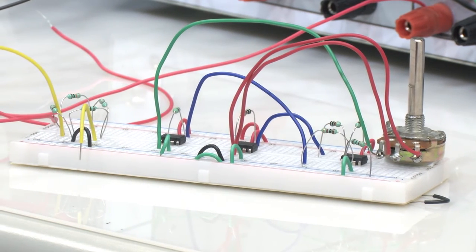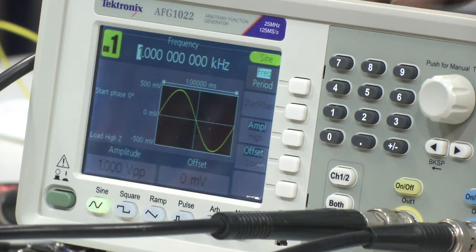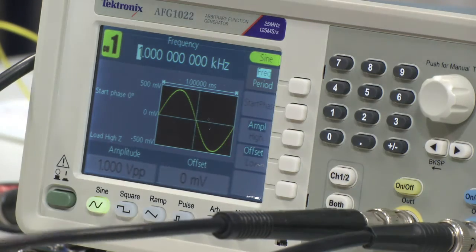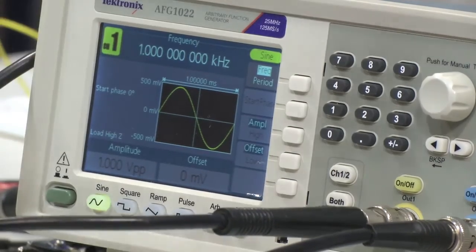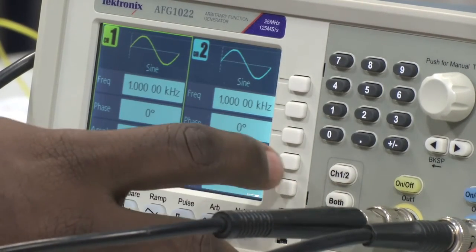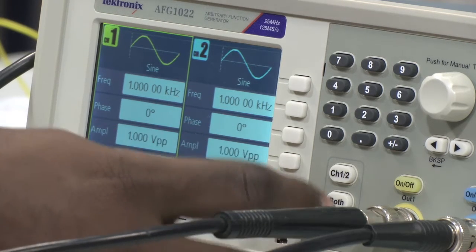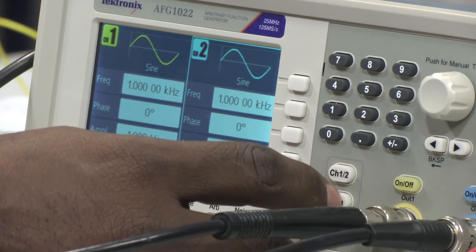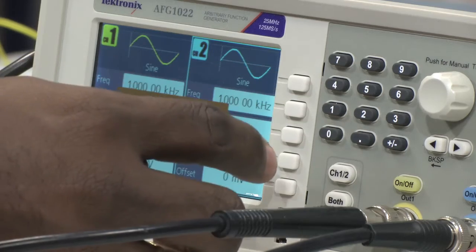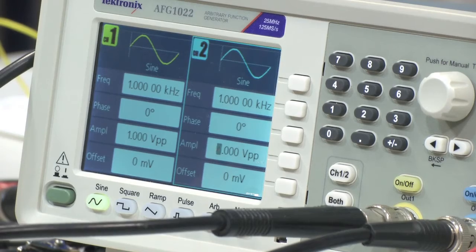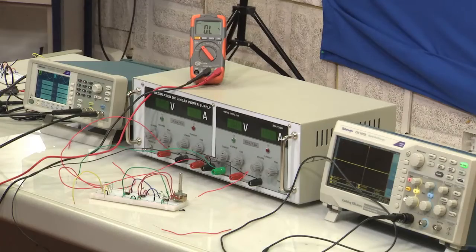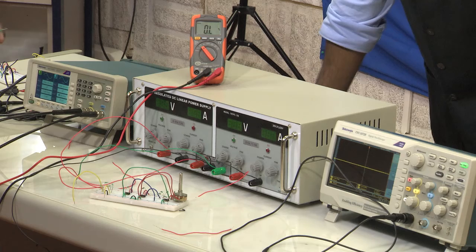We have seen in the previous experiment 1 volt, and now you can see here the signal from channel 1 is 1 volt peak to peak. Yeah, and now connect to channel 2 please. And let us see both the channels together. Yes. So, for channel 2 apply some different voltage. Okay. So, you can see channel 1 is 1 volt, channel 2 is 2 volts. This is what we are applying to the instrumentation amplifier at the input.